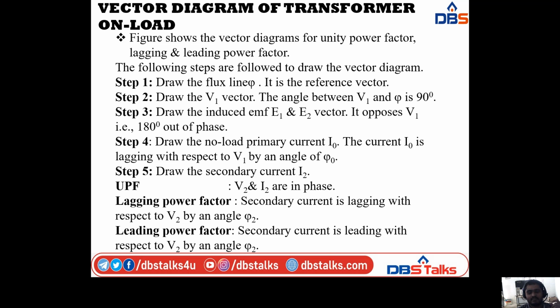I will follow some steps to draw this vector diagram for the transformer on load condition. First step, I am drawing the flux line phi, which is the reference vector. In the earlier slides, I showed a step-by-step procedure to draw the phasor diagram of the transformer on no load condition. In this one also I am taking the flux line phi as the reference phasor.